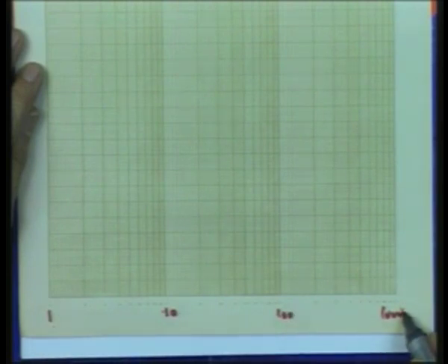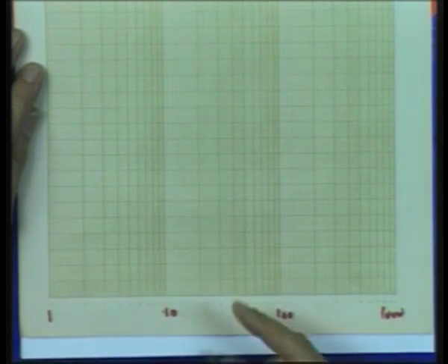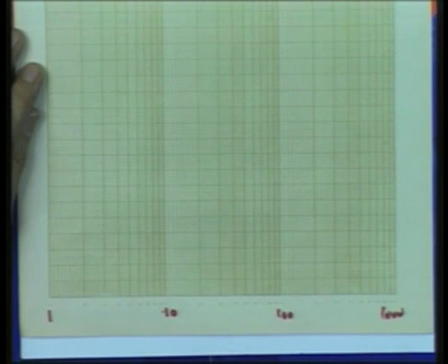100 radian per second, 1000 radian per second, or I can use hertz, cycles per second, also, except when I talk about corner frequency I have to be careful about the choice between omega and f. It is omega which is equal to the absolute value of the real zero or the real pole, not f. So, if I keep that in mind, there is no problem.